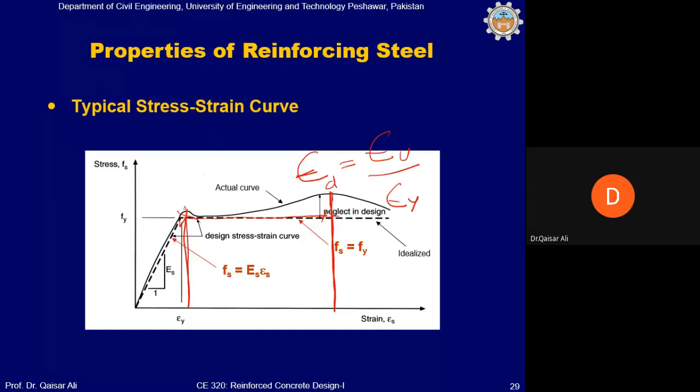So the larger this gap, or the larger this ratio, the higher the ductility of the steel will be. So the strain ductility is a measure of better performance of steel, because ductility is a desirable property of steel. We would like to have ductility in the steel that we use in our projects. So two things we should remember from this slide. One, that yield strength will be used as the strength in our calculation, not the ultimate one. And the remaining strength will be kept for the purpose of ductility as a reserve strength.